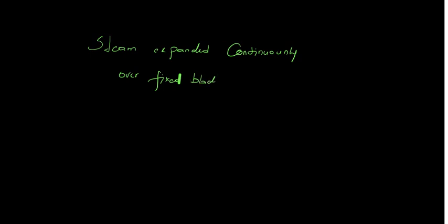Steam is expanded continuously over fixed blades and moving blades. Right? When compared to the impulse turbine, we don't have the continuous expansion of the steam, right?